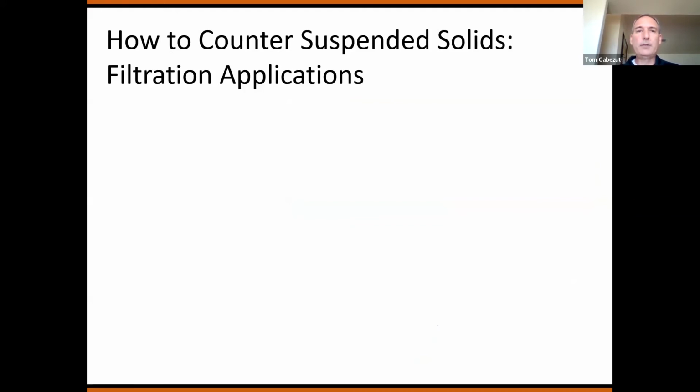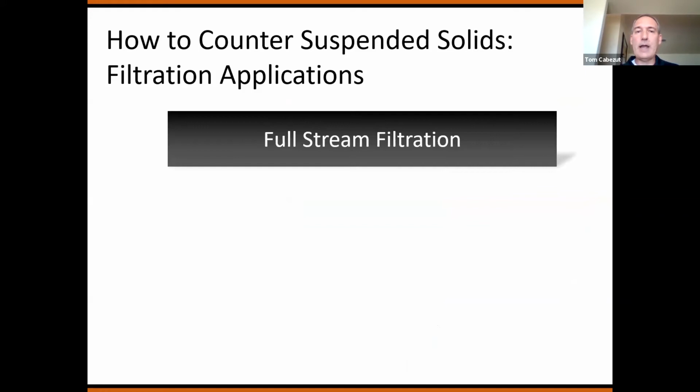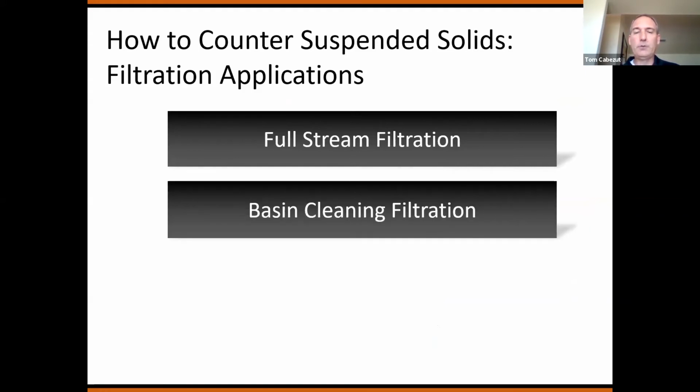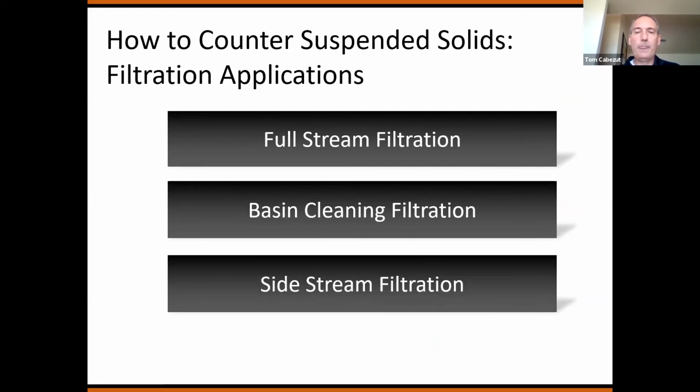So how do you counter suspended solids? Filtration applications specifically, you can do full stream, basin cleaning, which is the one we're going to focus on in the next few slides, and side stream. Full stream is 100% of the flow, basin cleaning sized on square footage, and side streams typically anywhere between 5 to 25% of your condenser water flow.